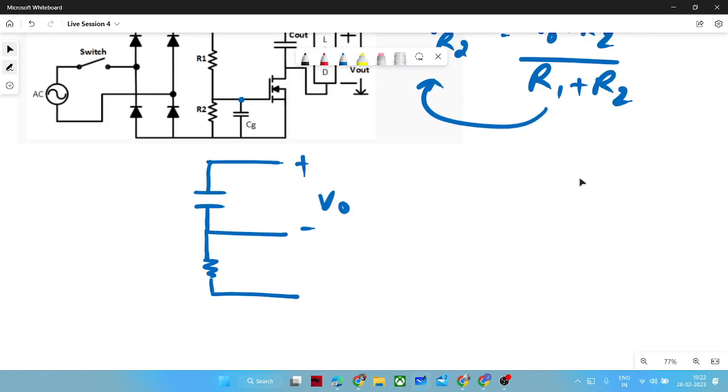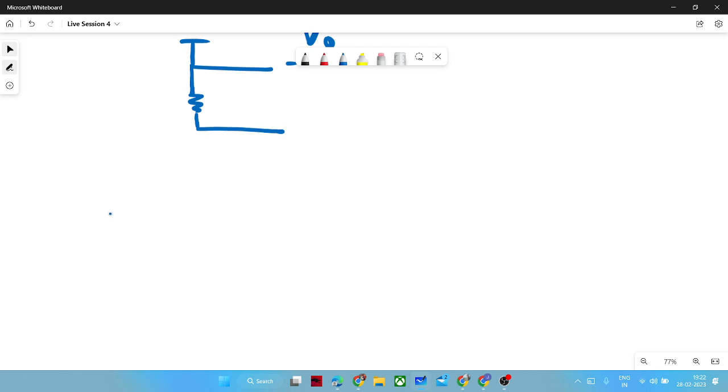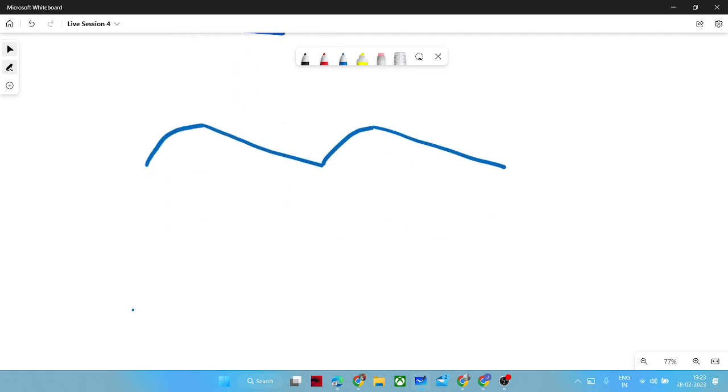No, see, steady state means whatever is happening in one time period, it is charging and then discharging and again charging and discharging. Whatever is repeating itself, right? That is a steady state. But what is happening at startup? Earlier, your inrush current was like that, and then it is dying down like that, after some interval, right?